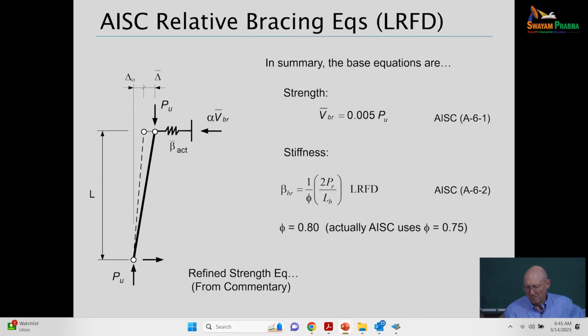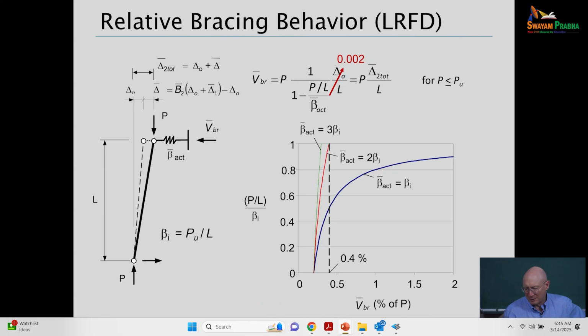And so let's get back to the plot here. When we provide more bracing stiffness than what we really need, the bracing force gets smaller once we get to the ordinate of 1 here at the top of this plot. So this plot basically gives us the argument that, yeah, we generally cannot just use ideal bracing stiffness. The brace force would become unbounded.